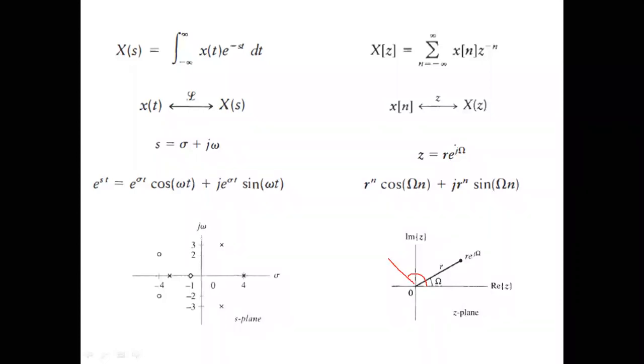Now let us straight away go to the formula of the Z transform and get started. So what is a Z transform, by the way? It comes with a very simple formula. You will be given an x of n, which is aperiodic in nature. That is why you will sum from minus infinity to plus infinity of x of n, z to the power minus n. That will be the formula.